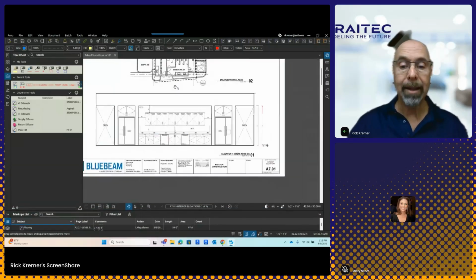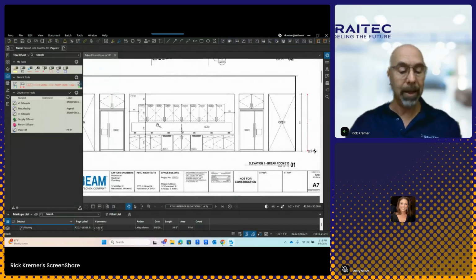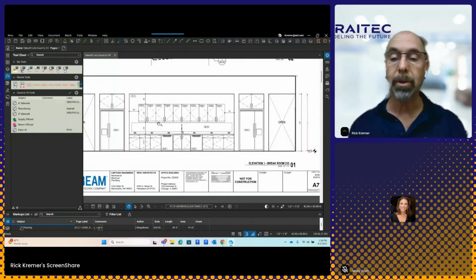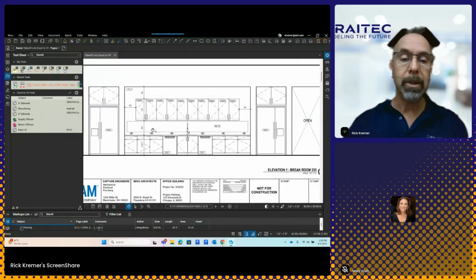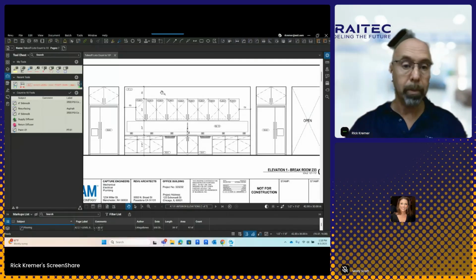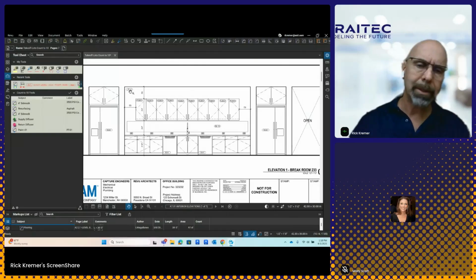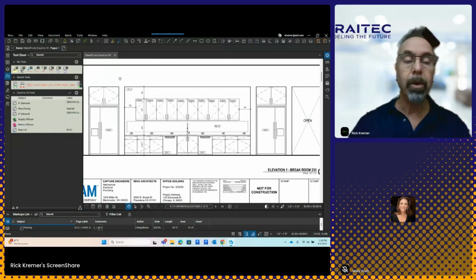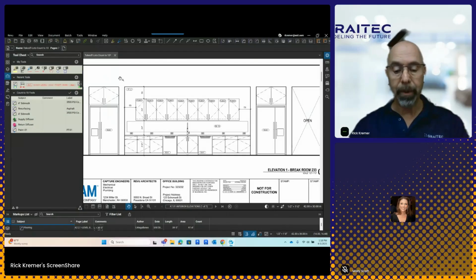Let's take a look at this area over here and do the same thing. And let's say this area here also is paint. But you'll notice that there's also glazing. I want to find out how much paint it's going to be required to paint this area on paint number 2, or let's just say it's paint 1. What I'm going to do is enable something called dynamic fill.